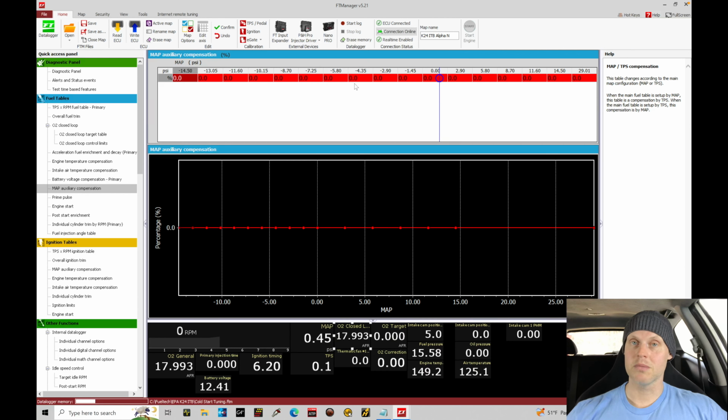Because the MAP pressure effectively is representing our baro pressure, because we don't have the MAP sensor, whether it's the onboard or the external sensor, measuring engine vacuum, but we're measuring atmospheric pressure, we'd be able to go in at whatever the elevation you're going to be at, whatever the MAP pressure is reading, and use that as an offset for idle, part throttle, and wide open throttle to get your fueling in line. Now, right now, I'm approximately sea level.